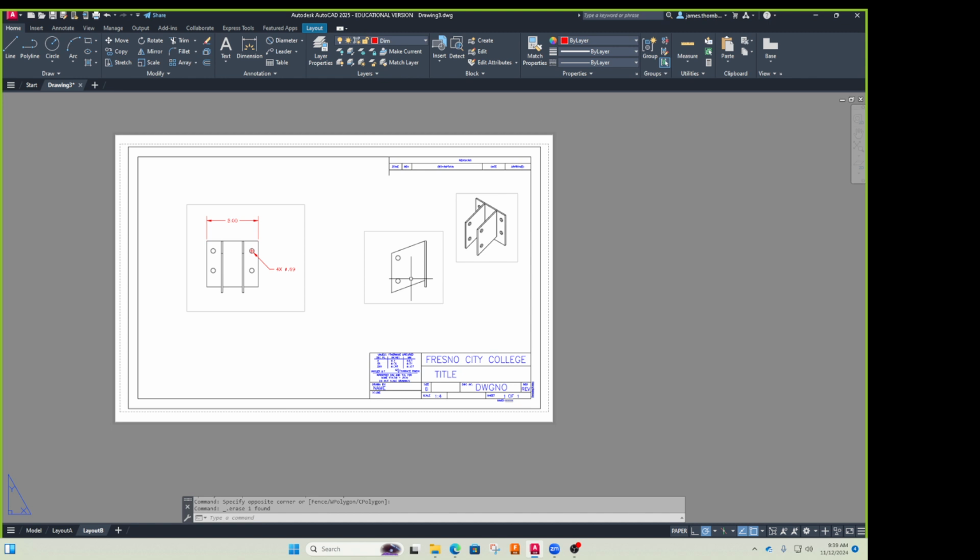The old school way was called MV setup, and you could pick on viewports and align them, and that was meant more when we were making views of 3D objects in here. But it's kind of cumbersome. This process, I'll just draw a line in paper space, move things, or use tracking and make them line up.